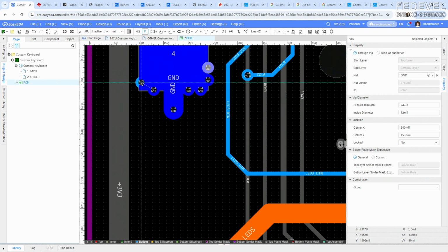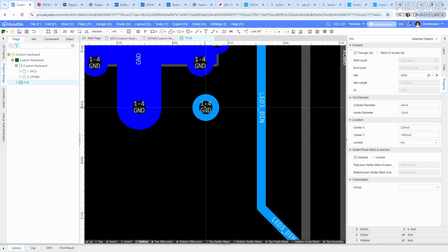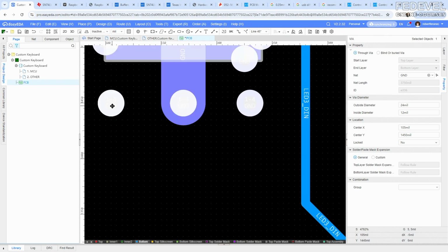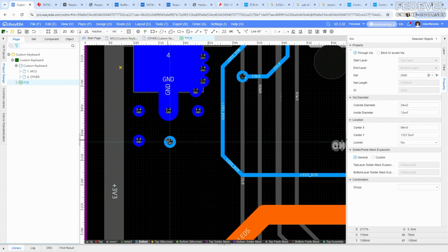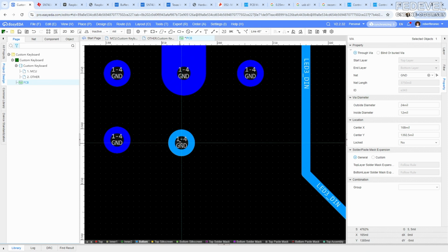And don't forget, this is a voltage regulator, a linear voltage regulator, so it may get warm or hot. So what I'm going to do, I'm going to place many vias here because we have two big ground planes inside of the PCB. They can help to spread the heat. And also we will make a little bit bigger copper pour here on the bottom side around the regulator.